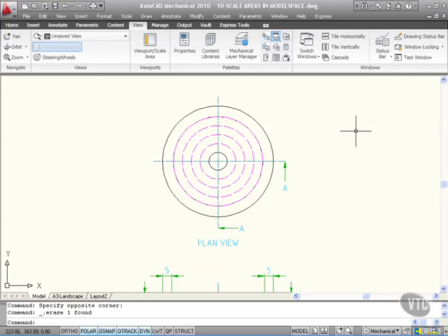Now, when you're working in Modelspace in AutoCAD Mechanical, you can actually set up scale areas in your Modelspace. Previously we've set up named views. These are subtly different. Basically what you're saying is, I'm creating a full size view in the model. So in the Modelspace it will be full size, but you're telling AutoCAD Mechanical what scale you want that view to be in your Layout tab when you create a viewport from that scale area.